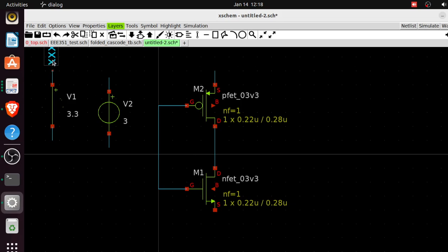I need a similar thing here, but their labeling will be different, and I need it here too. So all I need to do is copy. I need it in several other places too, so I'll copy this multiple times. You select by clicking, then press C for copy, and it's copied. Same thing, C for copy and copied.